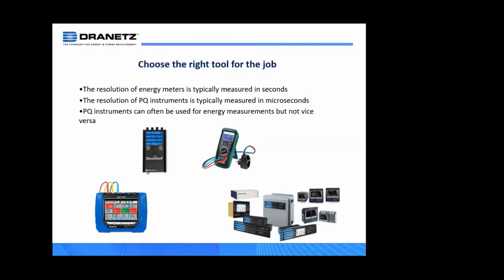And then, of course, when we go to PQ instruments, their resolution is typically in microseconds, which makes them suitable for recording power quality faults. But again, they can also be used in energy applications, because for energy applications, microsecond resolution is more than enough to provide accurate data.